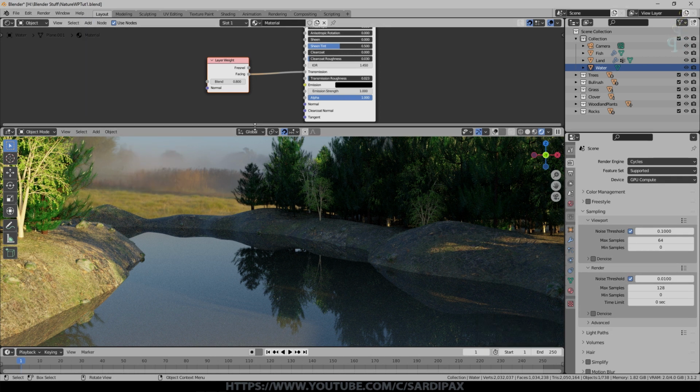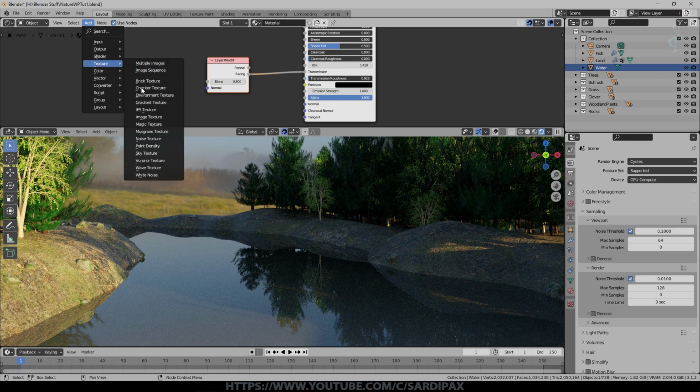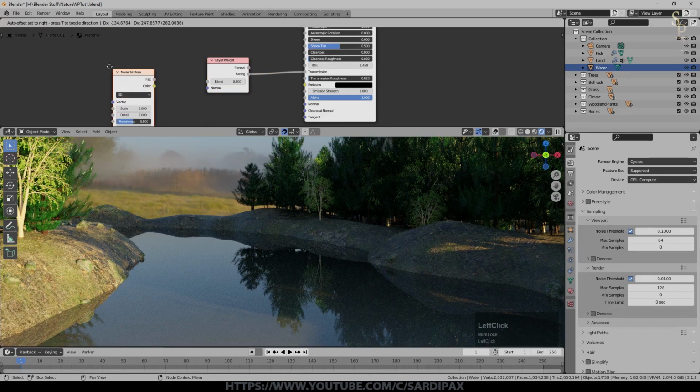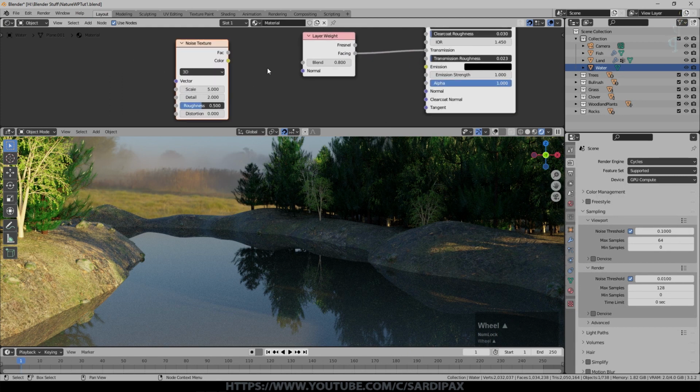And there's various different ways of doing this. In the past I've done it with purely a wave simulation, or distorted waves, or a combination of wave and noise. But for this one we're just going to use noise, as I think that gives a reasonably good appearance. So under texture we're just going to add a noise texture. Where would we be without that node? Certainly it would be difficult to do nature simulations.